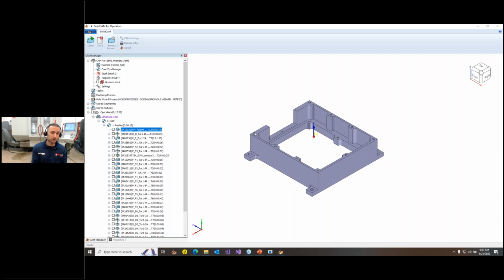But when you talk about 3D operations, we delete the facet models that we use for 3D calculation. So you're not going to recalculate 3D and 5-axis operations. So once again, the answer would be like the other thing with making operations. Technically, you could do it in some limited situations, but that's not what it's meant for. And there's going to be lots of things that it can't do. So once again, CAM programming should always recalculate the part, open it up, close it from SolidWorks or Inventor, and have the part prepared.